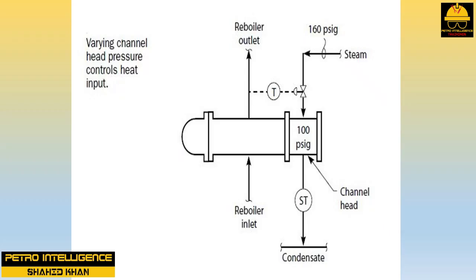Condensate pumps are sometimes used to overcome such back pressure problems. However, these pumps are often not kept in good repair, and condensate is still lost to the sewer. Eliminating the steam inlet control valve of the type shown in this picture has helped recover condensate from many reboilers supplied with low-pressure steam.